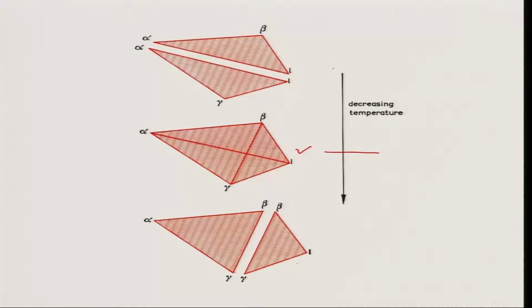What I am saying is that these 2 can be either peritectic plus eutectic, or both eutectic. If it is peritectic plus eutectic, that means liquid plus alpha will react and form the beta phase for the first 3 phase equilibria. For the second one, liquid will transform directly to gamma plus alpha, correct. Otherwise, both of them can be eutectic also.